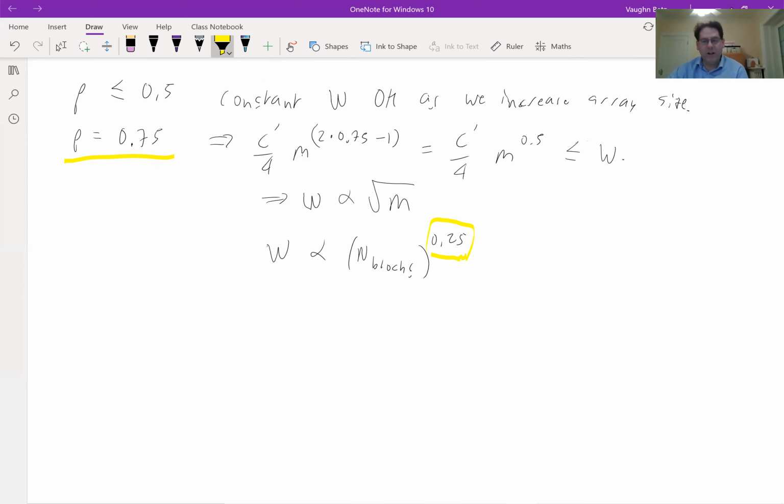10 times as wide a channel is more area for sure. So your area per logic block plus the associated routing has gone up quite a bit. But you did increase the capacity of the chip by 10,000 times, and you only had to increase the width of the channel by a factor of 10. So it grows pretty well. So the key thing is that the channel width doesn't have to rise very rapidly. It's a slowly growing function.